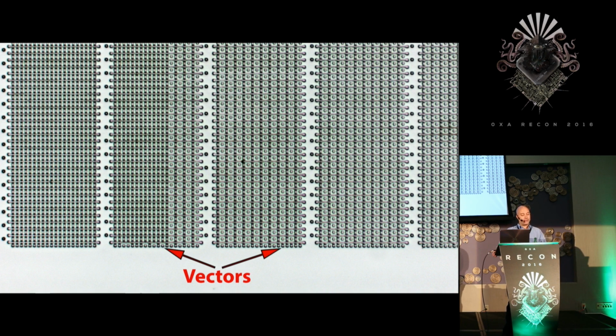So after extracting the bits and decoding them into bytes, the hex dump can be studied. There is a copyright 1997 CHCC ASCII string in ROM, so this is very helpful to identify when you've actually decoded the ROM correctly. The decoding is just a matter of organizing the bits into bytes, and it's in a really straightforward manner. There's no scrambling or anything like that.